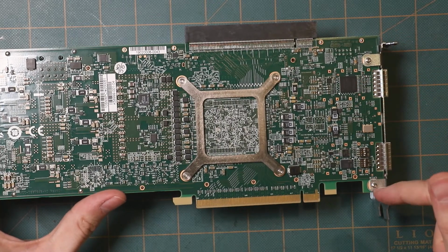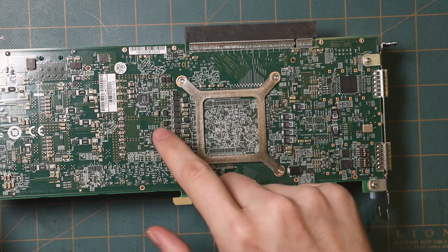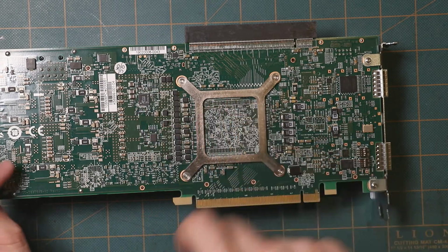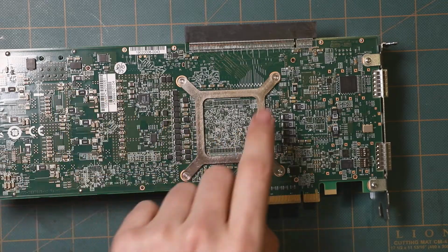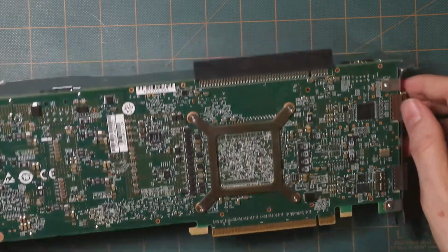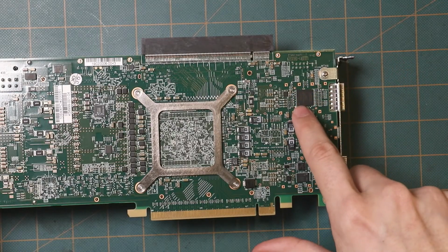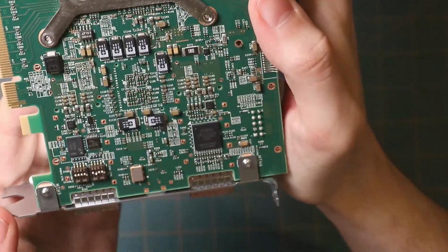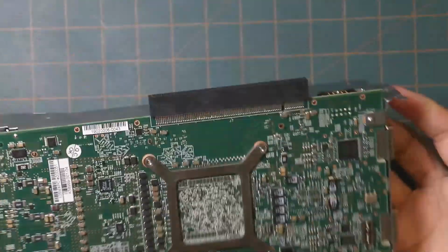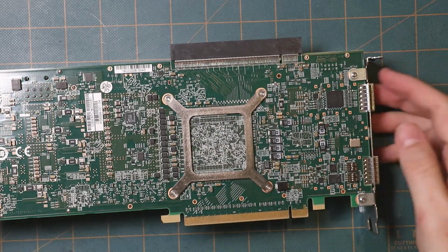Okay, so what have we got over here? Again, like the other one, there's not very much on this board. Most of these components on here are all related to power. All of these big resistors are just current sense resistors for power supplies. And then there's other, like there's Linear Technology components and maybe some level translators. There's also another MAX 10 FPGA. I think that's what that is anyway. Presumably, yeah, that looks like a MAX 10. That'll be for the board management and JTAG. And that's about it on the bottom.